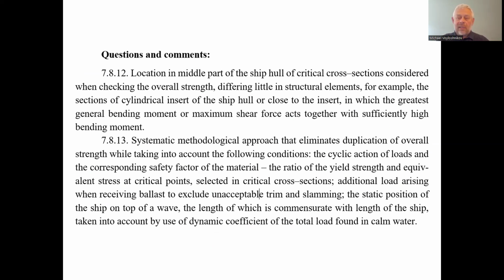So when we consider the factors impacting the state of the ship, the shearing and the general bending, we have to assume that it is not very probable to consider other factors simultaneously sometimes, because some of them exclude the other factors. As we said, the factor of slamming causes the possibility of fatigue failure of the ship by the cyclic loads.